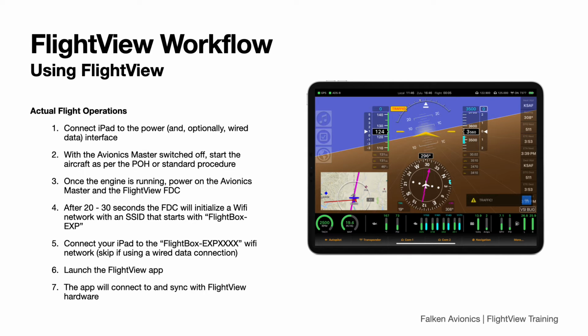Give the system a few seconds to boot up, and then, if you're using Wi-Fi, go into the iPad Settings app and make sure that the tablet is connected to the Flightbox-EXP Wi-Fi network. If you're using a wired Ethernet connection, you can skip this step. Finally, launch the FlightView app. Note that it can take a few seconds for the app and the back-end hardware to sync up.